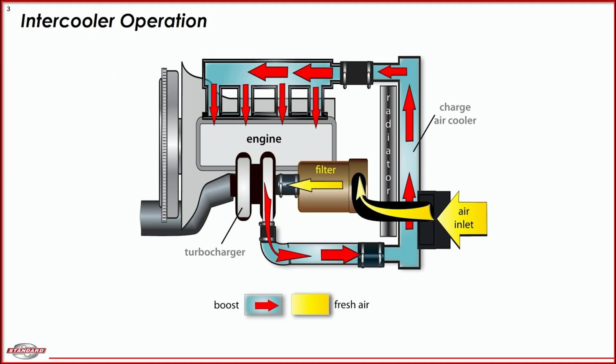Now, with that said, we understand that the turbocharger works by compressing air, right? We're going to be spinning that compressor wheel. It's going to be compressing air, and that's going to create a lot of heat, right? And that's why it's important that we have an intercooler. We saw that behind me just a moment ago. Intercooler, charge air cooler. These are super important because of the amount of heat that is created. It's simply the law of thermodynamics, and it's present really in any turbocharged engine application, even on low boost settings. So we've got to remember that even on low boost, we're still going to have that heat. So the incoming air charge has got to be cooled down before it can enter that intake manifold.